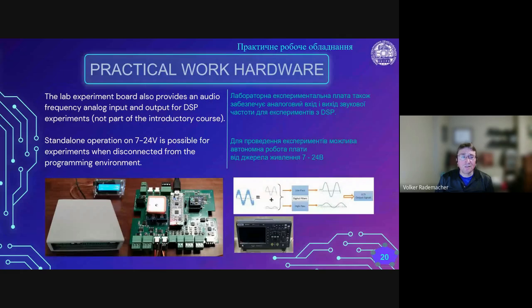One thing: the DAC output on one of the processor pins can be jumpered over so that it can also be used for a DC digital to analog output, for example, controlling other devices that need a variable DC voltage for controlling them. But otherwise, it can be used for generating sine waves, for generating, for example, DTMF. And the input can be used to implement filters.